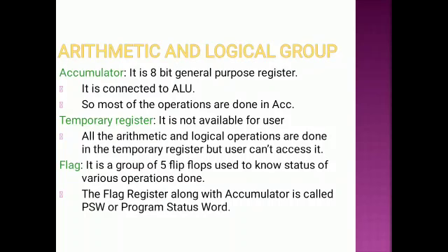Another is the temporary register, which is not directly accessed by the user, but when the processor performs any arithmetic or logic operation, the data is loaded in the temporary register. Next one is the flag. Flag is actually a set of flip-flops which are set or reset depending upon the various operations performed by the processor.